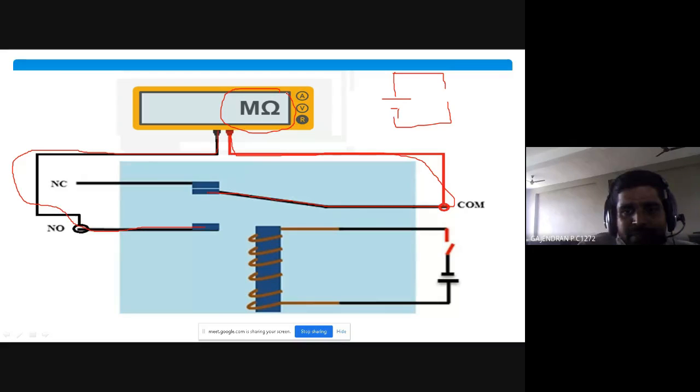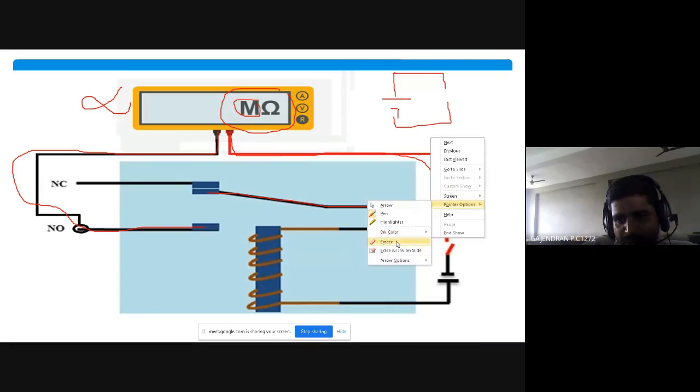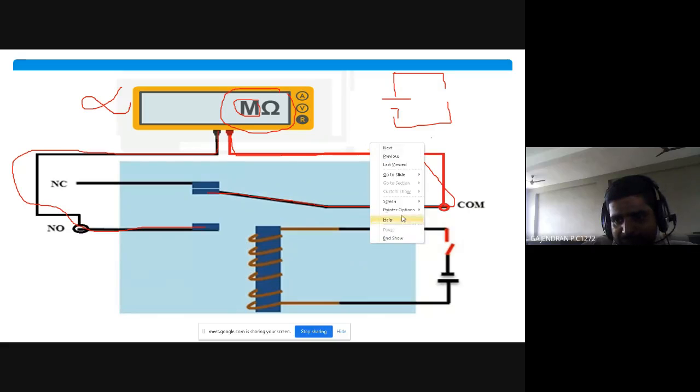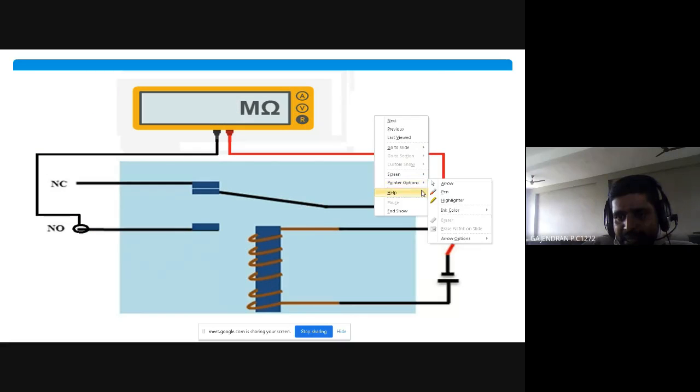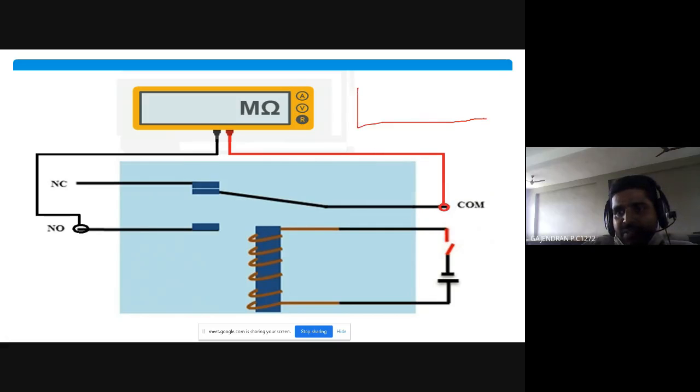If my circuit is an open circuit, it shows infinite ohm. In digital multimeter, it is not possible to make the infinity symbol. Therefore, it shows mega ohm. If you see in the real multimeter, it won't show mega ohm. Can anyone tell what it will show? What will the real multimeter show, sir? For infinity it will show 0 in the last digit.